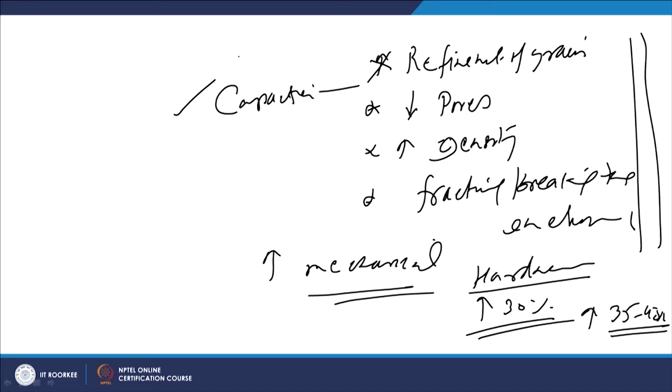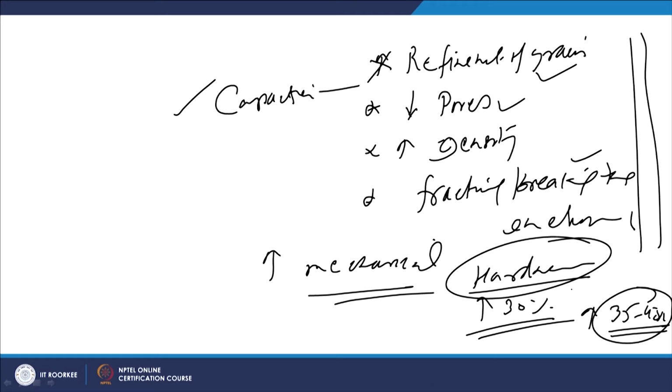That is the obvious part: if things are getting refined, pores are eliminated and inclusions are fractured, then this will increase the coherency and stability of the coatings, which will increase the hardness, and increased hardness will lead to improved wear resistance.